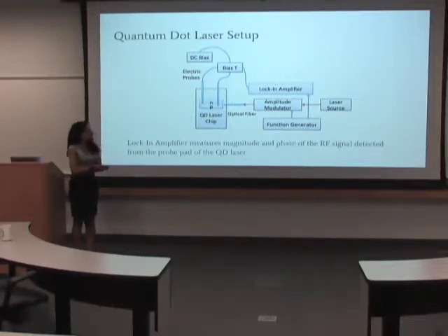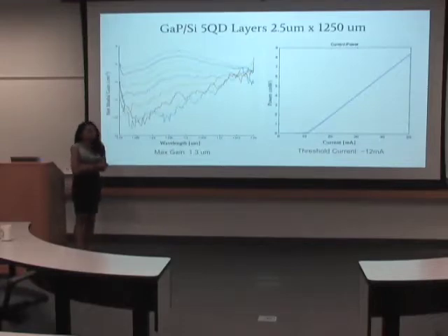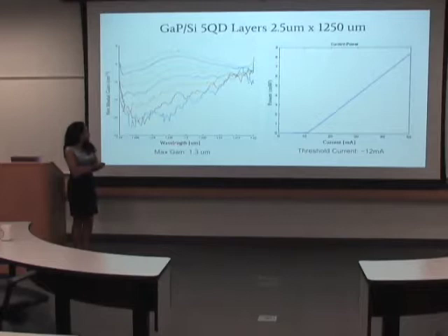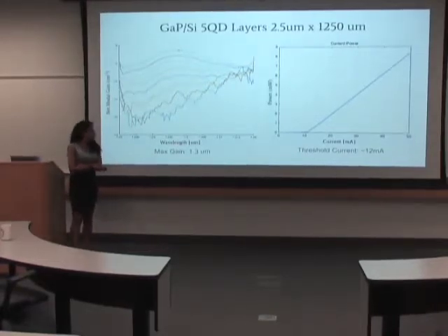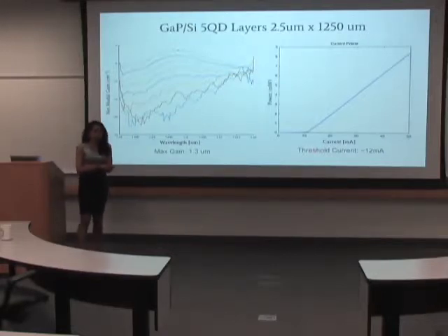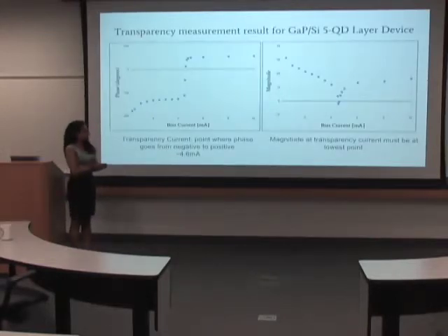After plugging this in, we were able to find the power coupling ratio. As you can see, this is a 50-50 device, so we were trying to get a 0.5 splitting ratio, which we were approximately able to get, but due to loss, it's slightly off, but as you can see, the device works pretty well. After measuring multiple devices, we were able to see that smaller length and width of the MMI allowed for optimal power coupling ratio, and that the angle made no difference to the ratio.